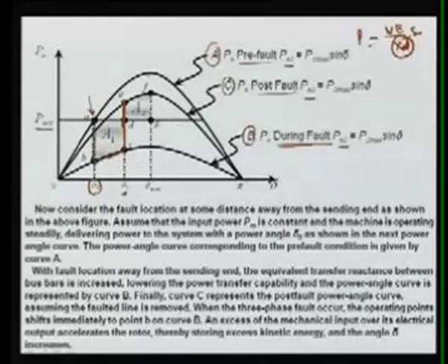And then this is your accelerating energy, this area, then it is going to decelerate till F, till the point when A1 is equal to A2, and then again it will go back and keep oscillating, and your final point of operation will be point K, because it will be oscillating around this point, and your system will be stable if damping is there and the oscillation will subside.